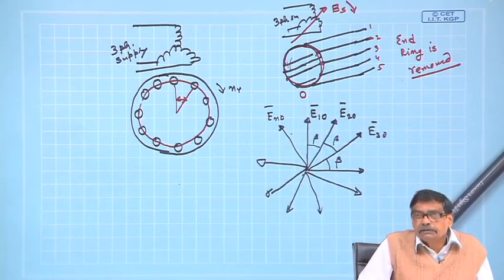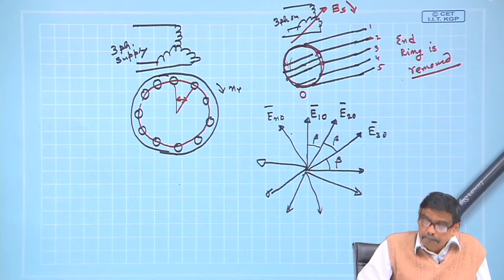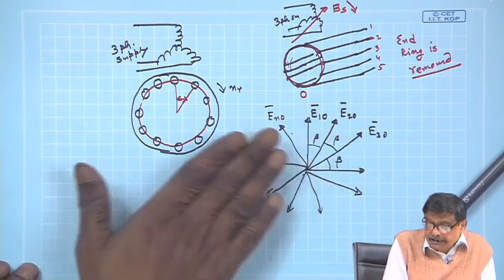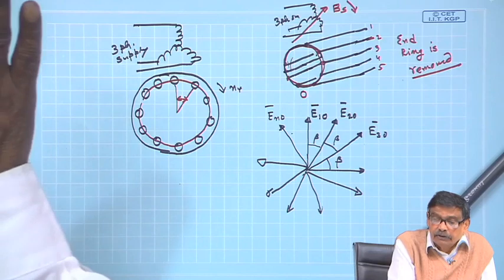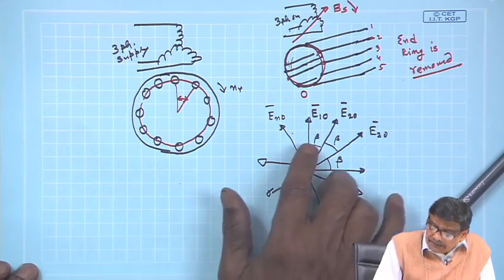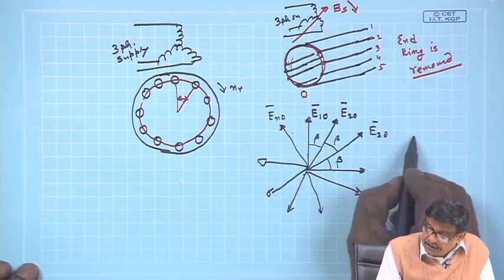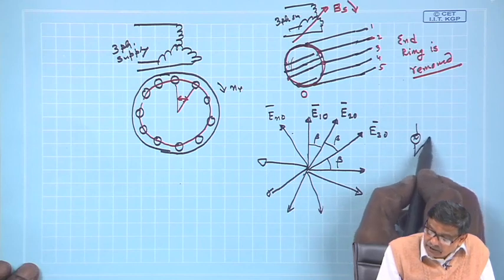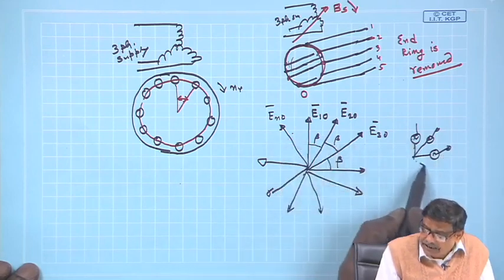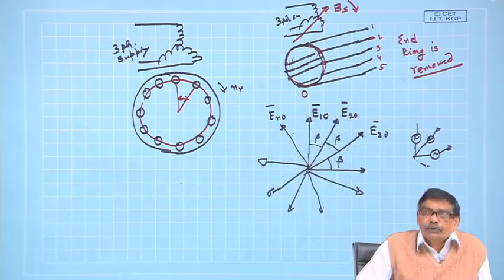Now, the argument is, so in the rotor circuit I have generated a balanced polyphase voltage. It is no longer a balanced 3 phase voltage as created in a slip ring induction motor rotor, R phase, Y phase, B phase, not like that, but nonetheless the voltages created in this conductor become seats of EMF, and it looks like it will be like this. There is a voltage source here, there is a voltage source here, these voltages, and so many. So, it is a polyphase balanced voltage which will exist in the rotor.